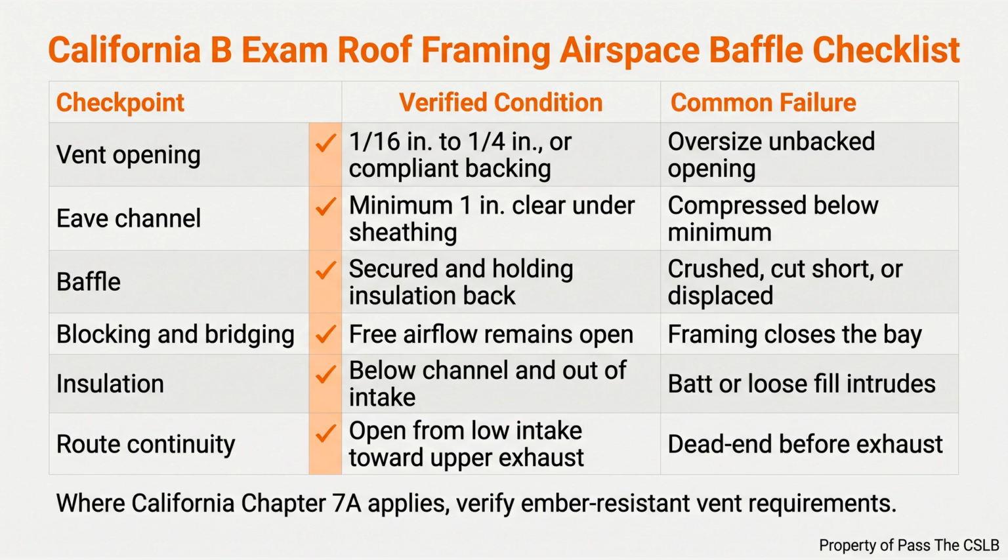Condensation is the reason the hidden air route matters. Warm interior air can carry water vapor upward through ceiling penetrations, attic hatches, recessed fixtures, and unsealed framing joints. When that vapor-laden air contacts a roof surface cold enough to reach the dew point, some of the vapor becomes liquid water on the sheathing or framing.